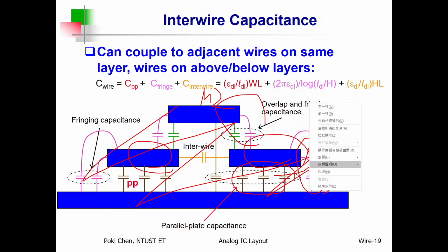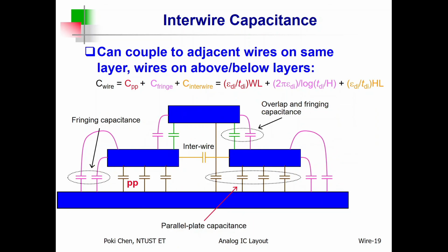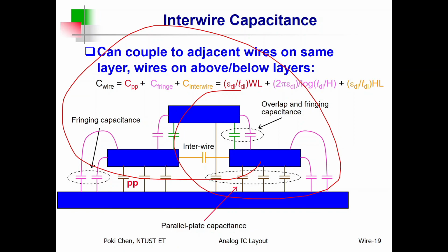Wow. It means you need to pay attention to all kinds of parasitic capacitance. That is too complicated for our brains. We are humankind. We are not machines. We are not AIs, right? So what can we do? Through the help of your EDA tools. But you are the one to make such kind of layout by yourself for full custom design, right? So try to simplify your wires, your routings, your interconnects as neat as possible to reduce all the parasitics. That is my recommendation.